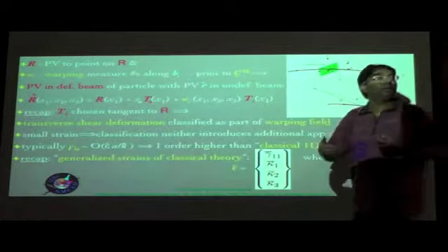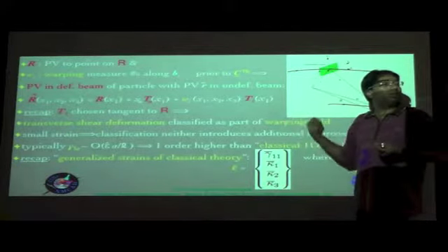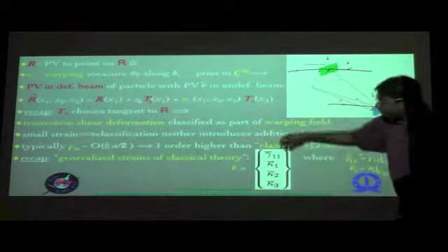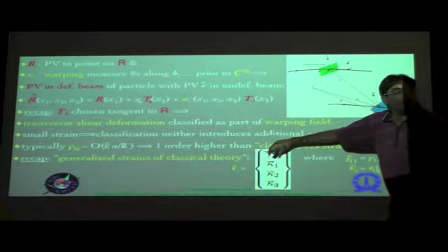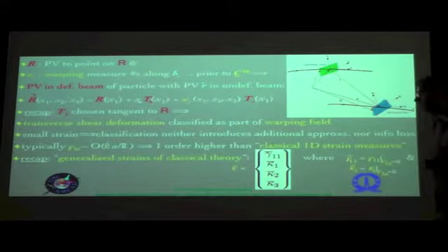The gamma 12 and gamma 13 are no longer 1D strains. They have been put into the 3D field, which is the warping, even though they are actually functions only of x1. So that's what we have, and so what remains is just 4 terms, only one quantity which is a force strain and the other 3 which are the moment strain, just as in the previous case.